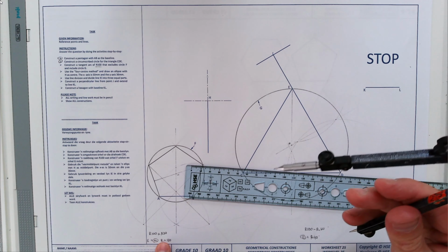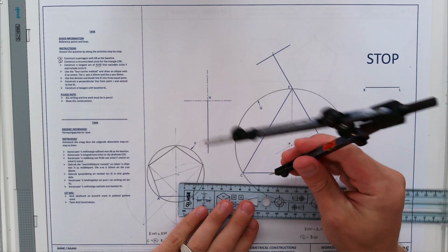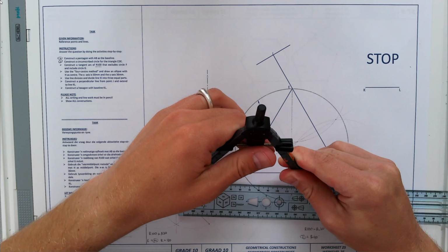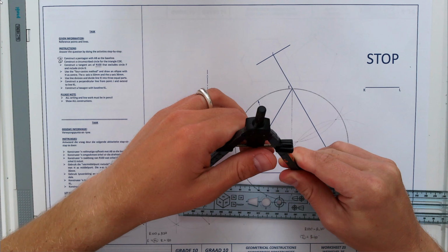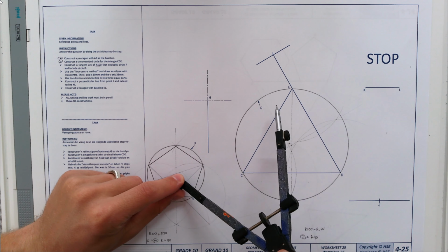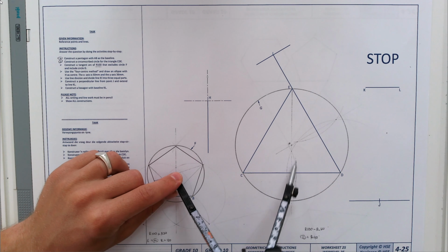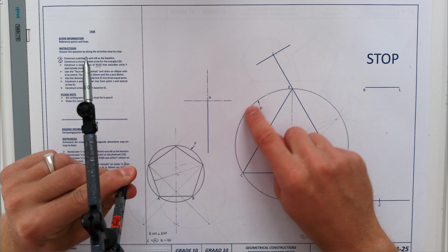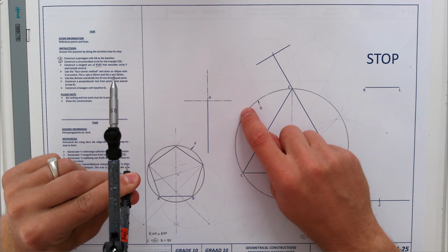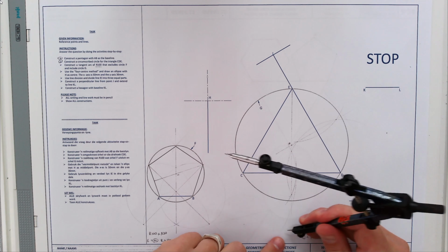So you're going to take your compass, you're going to set it on this 130 for circle F. 130. You're going to put your sharp point at M here at the pentagon. We are going to draw a light arc down here because we want this tangent arc to connect in this format or direction, excluding this circle, including this circle. So we want to put our sharp point here. So this is why I project this arc downwards.